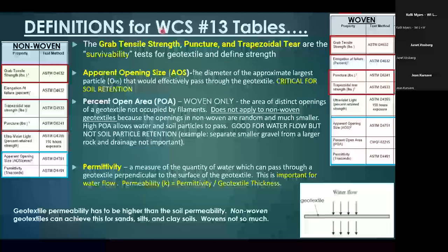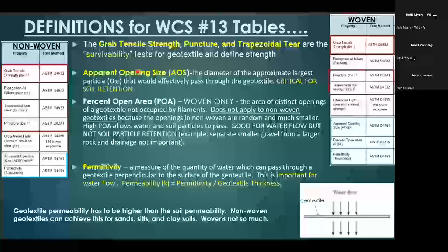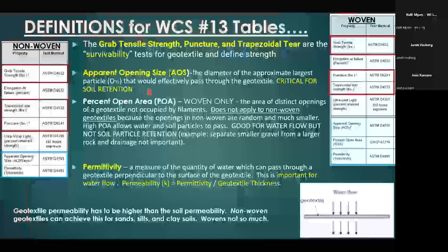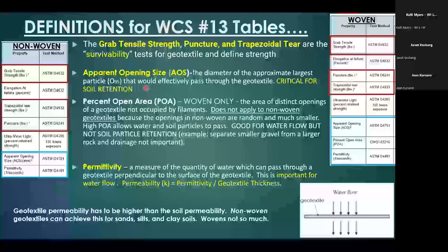Those are important to us, but things that AASHTO puts in their subtables that are less important, I guess, to road builders are things like apparent opening size. And this is what we need to have for keeping soil in place, that filtration feature. Permittivity is another one. That's the drainage one. Our projects, we like to be able to have drainage and soil retention as being 2 of our bigger things here. And what permittivity is, is basically how much water can that pass?